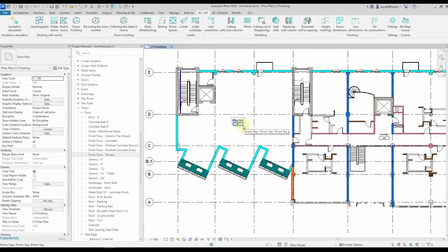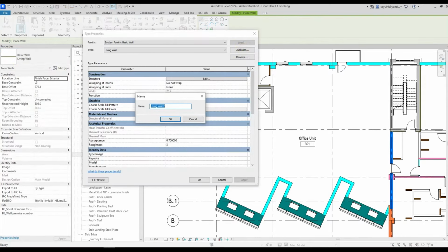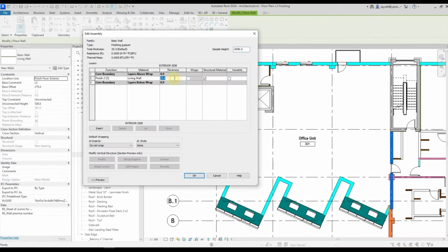So, to model some kind of finish, you have to prepare that type first. To apply a certain type of modeled walls, we need to create it. Let's do that. Let's take the wall, picking like any wall. Copy that type, name it, for example, drywall finish. Let it be a 20mm thick finish. We can specify layers right here, materials, and so on. I won't be doing that yet, but you can specify whatever you want.